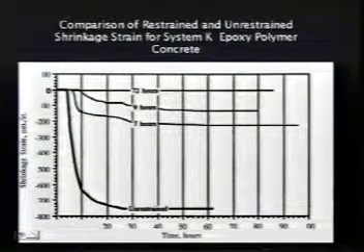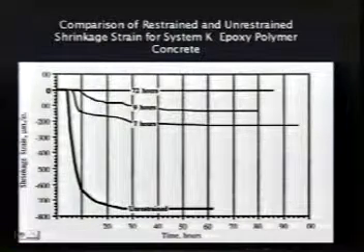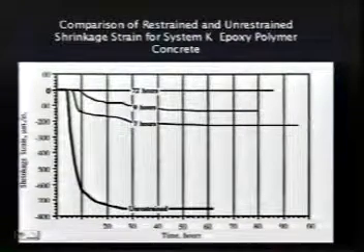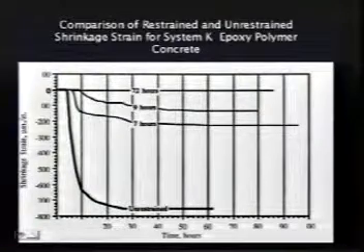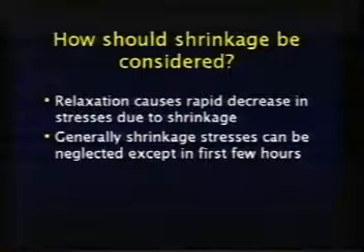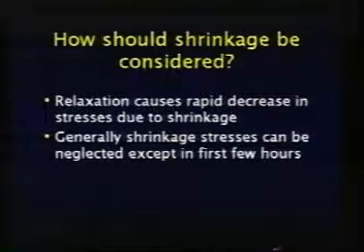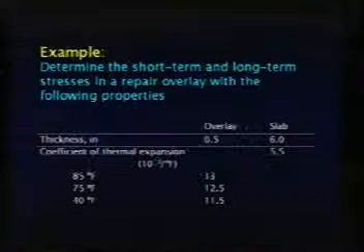So that told us that the shrinkage was pretty well absorbed in a matter of a few days. This happened to be an epoxy polymer. Generally, epoxies don't shrink as much as some of the other materials. But from those results, we decided that it was pretty clear that relaxation causes a pretty rapid decrease in the stresses due to shrinkage. And so it appears that we can neglect shrinkage stresses except in the first few hours, maybe for a very short-term scenario.